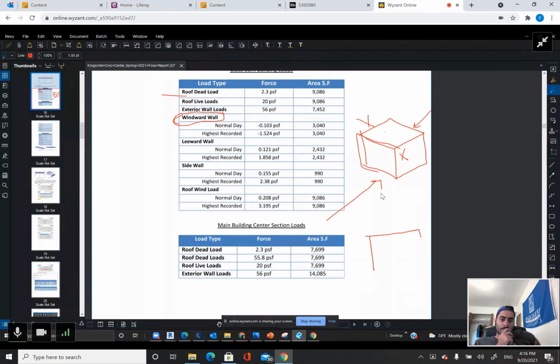If you look at a building, and wind is coming to it, it'll go up and over and around. And then here, it'll create negative pressure that pulls load up, that actually pulls the building up. On this side, you get similar negative pressure here. And then here, you're obviously pushing right at the building. The wind is just hitting it. The sides also behave differently.